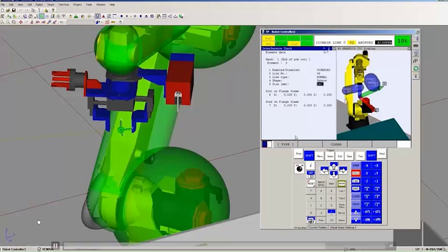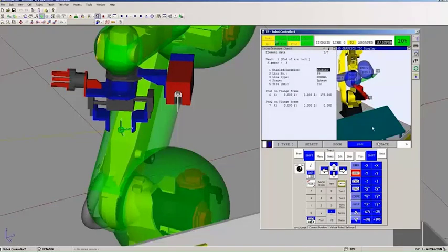I'll set the size to 150 millimeters and the Z value of the position to 175 millimeters. That's basically 175 millimeters from the faceplate. Press apply, and the view updates in the 4D graphics editor, and I think I have my hand model taught.